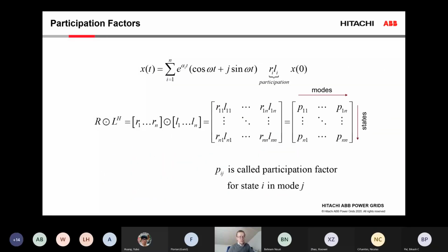Once you have those definitions of the damping ratio and the attenuation, the final thing to look at are the participation factors. We talked before about the real part of the eigenvalue that predicts stability or instability. We talked about the oscillatory part that predicts the resonance frequencies, and you see there is another gain factor here, which we call a participation factor.